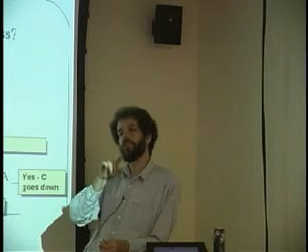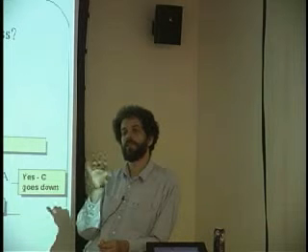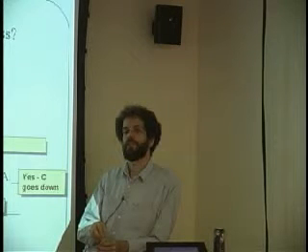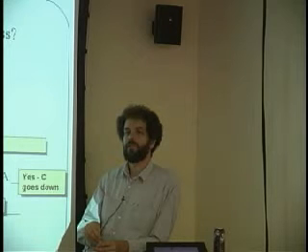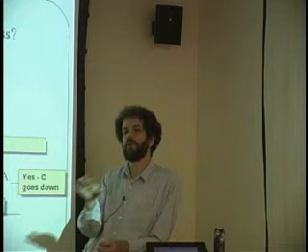If the voltage on the input and the capacitor is the same, then the time will also still be the same. So RC says what the time constant is, independent of what the voltage is that you're trying to do. So whether or not you speed things up depends on the relationship between the power supply and what voltage you want the capacitor to get to.